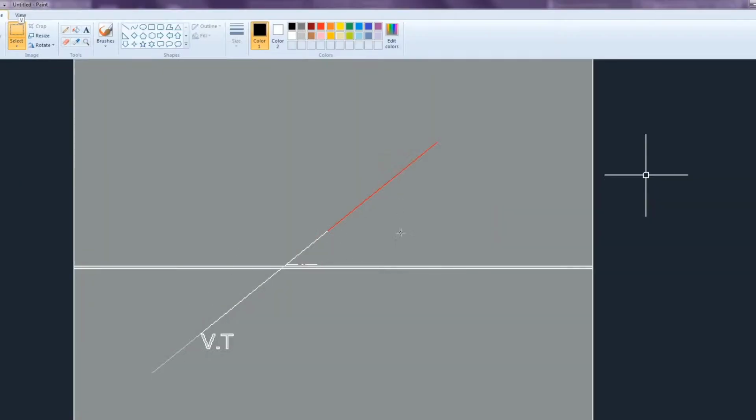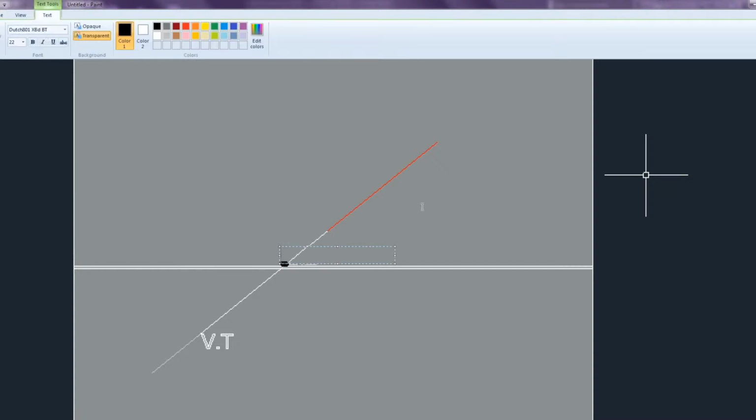See here, if it is a front view, when you watch this line's extension, it will look like a small circle. That's V when you watch it from the front view. From the front view you can actually see the vertical trace, and here it is going to be point H, because that actually belongs to the horizontal trace.